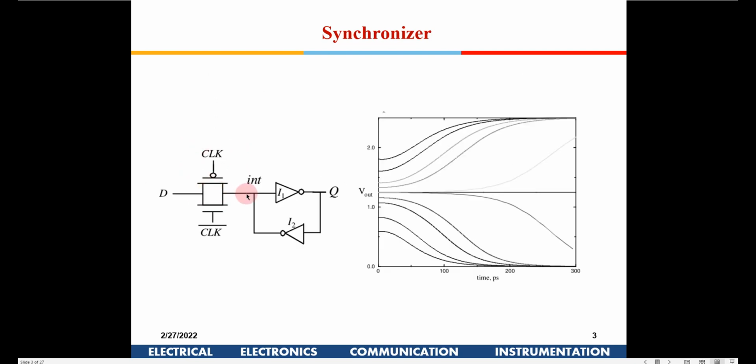Because this is coming from an inverter or some static logic, like we saw the delay equations in VLSI, where this is like a delay. This point gets charged, either it goes to 1 through a PMOS and the load capacitance gets charged. Similarly, if it is going to 0, it gets discharged through the NMOS resistance, right?